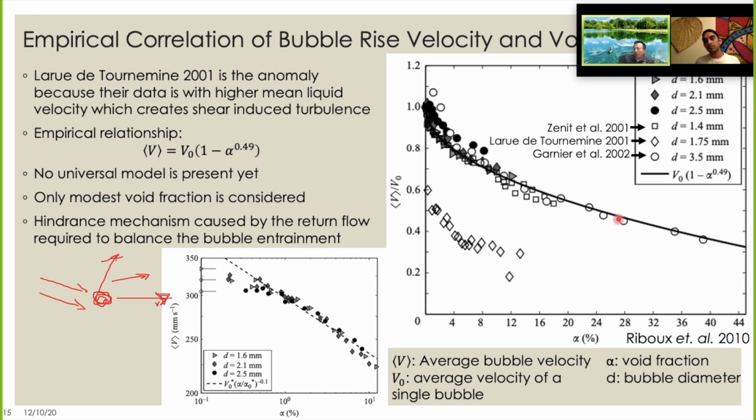So if I understand it correctly for this work, they do experiments separately. First, they only have the bubble, and they use the LDA to measure the bubble velocity, and then they add tiny particles in the background flow to get the flow velocity using PIV. That should be the way they did the experiment.